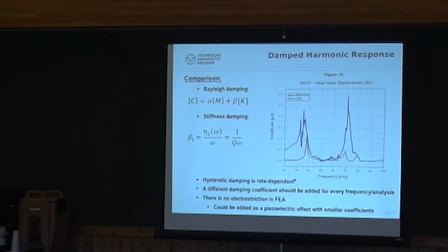So this had to be implemented for a frequency-specific simulation. This gives me a pretty good order of approximation when I compare the amplitude of vibration as tested on the optical table with the laser and with my FEM simulation. So 50% accuracy, I would say. But of course it can be improved. But the most concerning is that the second peak is missing.